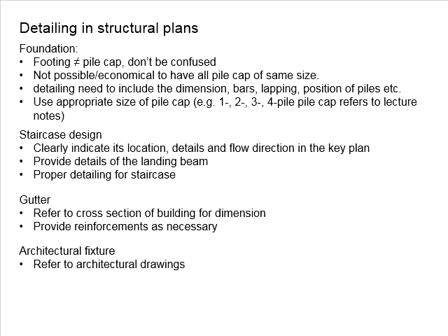In this video, we're going to proceed with our discussion regarding the detailing of the staircase. We will demonstrate some examples of the staircase detailing for better understanding. For the detailing of the staircase, you need to clearly indicate its location, its details in terms of the dimensions for the riser, for the steps, as well as the floor directions in the key plan.